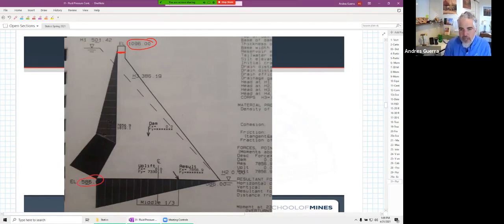So we're 510 feet tall. This is a program that calculates all the hydrostatic fluid pressure that's acting on the dam. This part right here, you can't see them because there's so many arrows, but there's all these arrows that are acting normal to the surface. Remember that our pressure is basically equal to gamma times H.